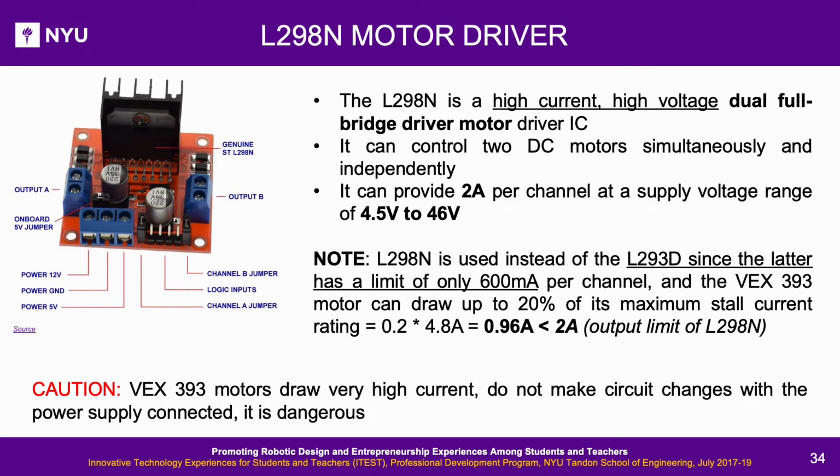L298N motor driver. The L298N is a high-current, high-voltage dual full-bridge motor driver IC. It can control 2 DC motors simultaneously and independently and can provide 2 amps per channel at a supply voltage range of 4.5 volts to 46 volts.